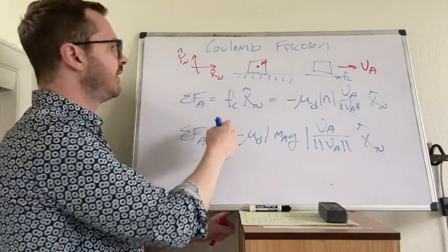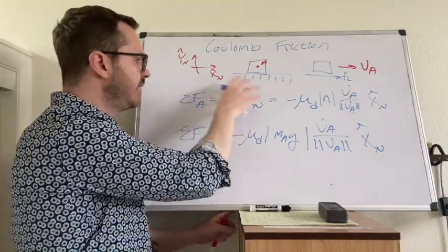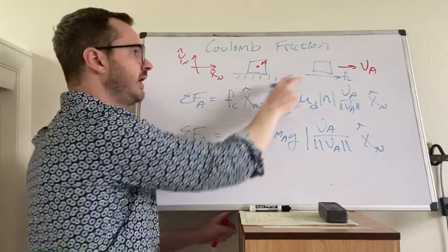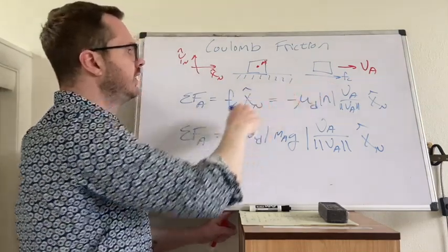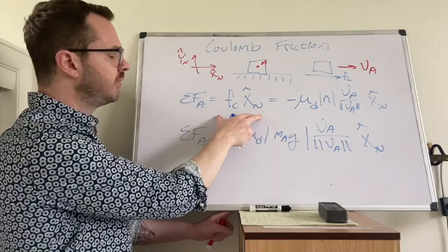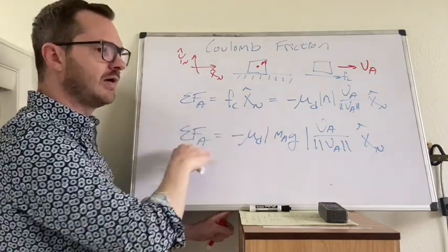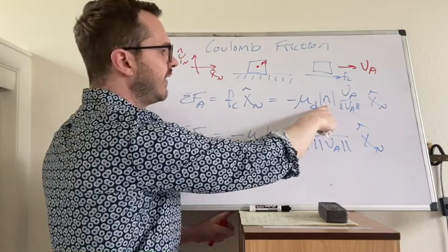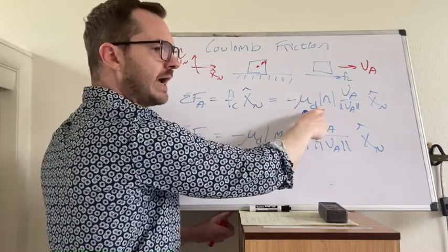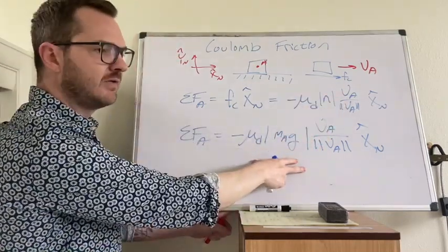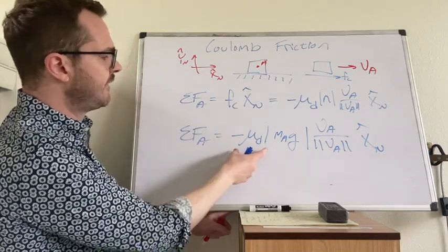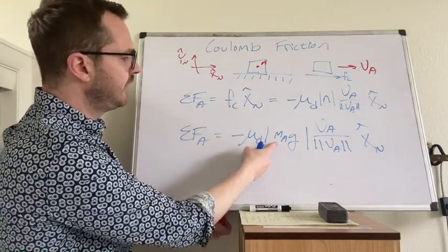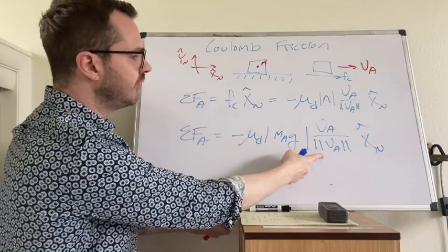We got rid of this kind of unknown Coulomb force, right? It's perfectly fine to write it down for free body diagrams and put it in sum of moments, sum of forces, and then you have to replace it with what it actually is, which is this. And then we had the normal force. Well, this is an unknown reaction force, so we had to put that in terms of something that we know. Mu d is now a constant, mass, gravity, these are all known.